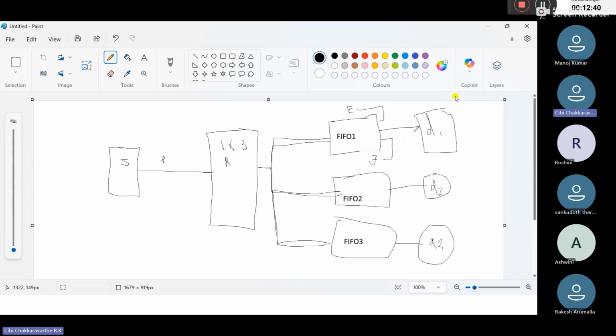If our destination is here and we are passing packets, and the FIFO is in the full state, we will stop passing the packets, so that our destination can process and take the next packets. Once the FIFO has some space, it will allow the packets again, so that we can perform smooth communication and avoid data loss.